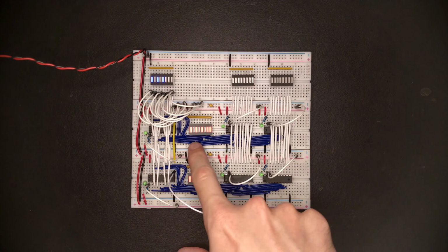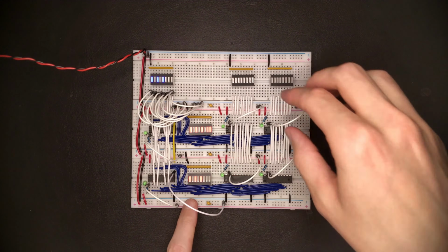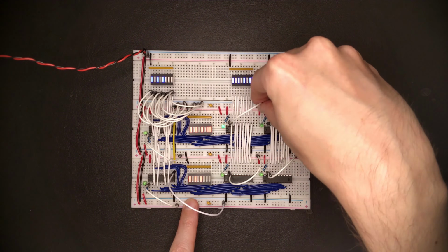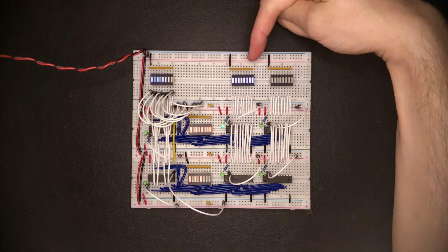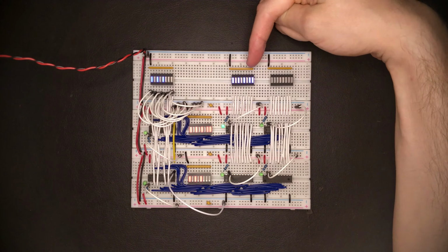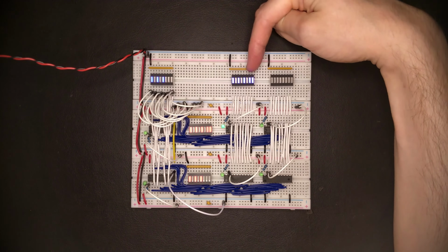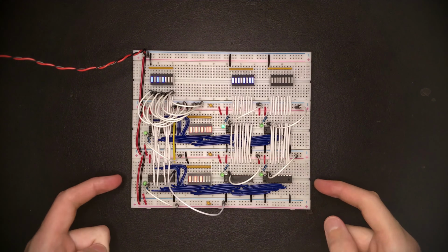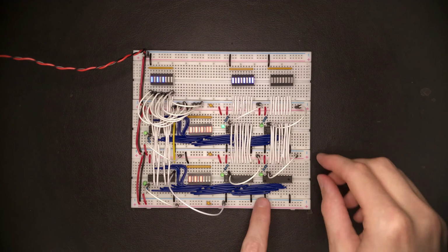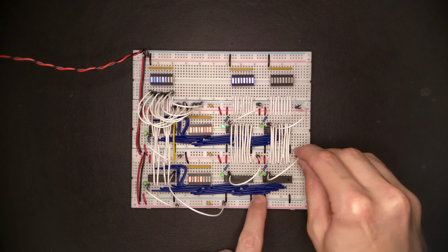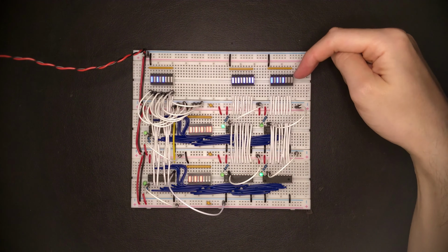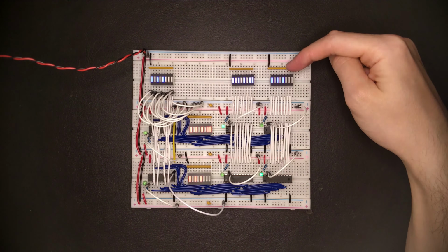So say we want to read the first register. All we have to do is pull low the output enable of that register corresponding to that output bus. And we can see the value of the register make an appearance here at the read data output port of the register file. And correspondingly, at the same time, we can decide to also read register 2. And all we have to do is turn on the corresponding output buffer. And the value of register 2 is displayed on the second read data bus.